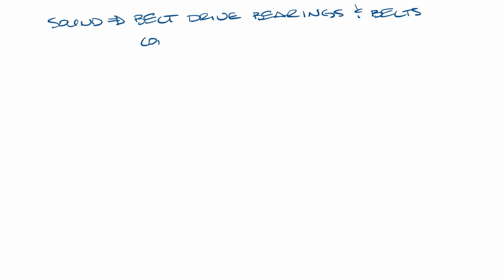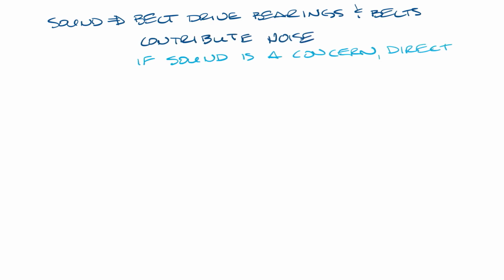Let's move this over. Another consideration is sound. Belt drive fan bearings and belts can contribute noise to the system, so if sound is going to be a major concern, direct drive might be the way to go.